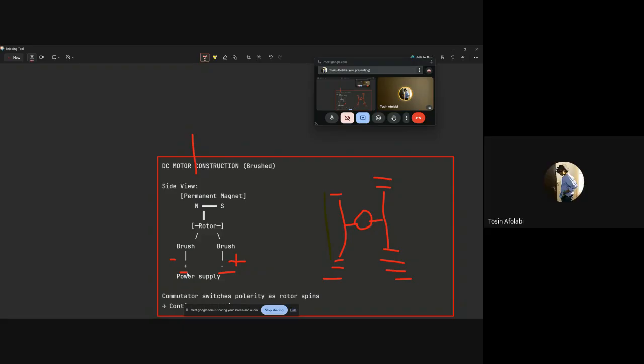Don't worry. So the H bridge, this ugly bridge right here, is needed to enable DC motors to work correctly. The motor is going to be the one at the center, where we have switch 1, switch 2, switch 3, and switch 4. The function of the switches is to control current flow in both directions.